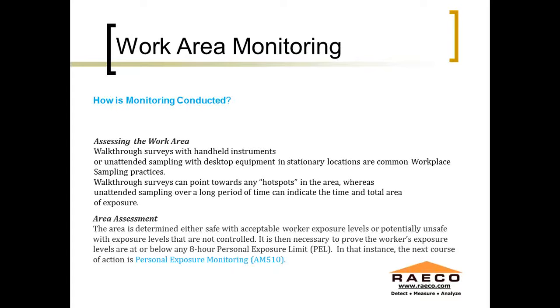Every year they take samples at specific points to identify if there's been any changes or anything happening to their engineering controls that would indicate further evaluation of an area. So they take a 10-second sample at various spots, which is something you couldn't do and really get any kind of accurate information without a long-term study using the gravimetric type approach.